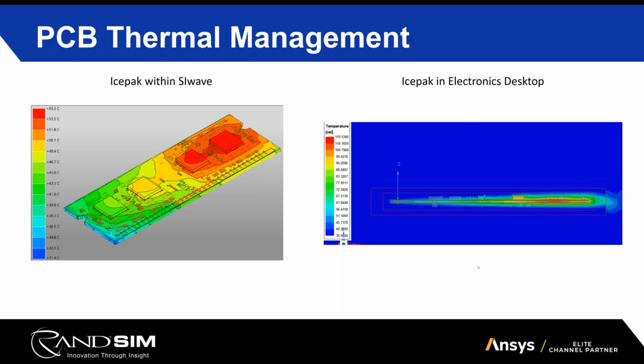There are two main ways we can use IcePack, our thermal software tool. We can use it as a plugin to SI Wave, which you'll see on the left. This is going to give us a power overlay of the board and the components that we can see within SI Wave. We also can use IcePack as standalone software. This is going to give you some more fidelity when looking into the thermal management.